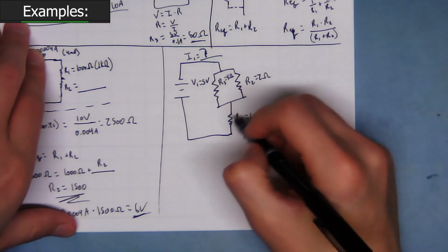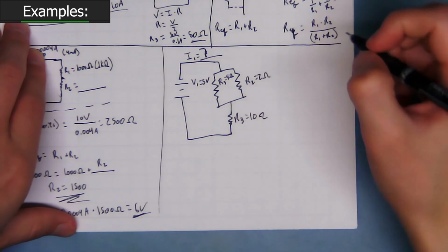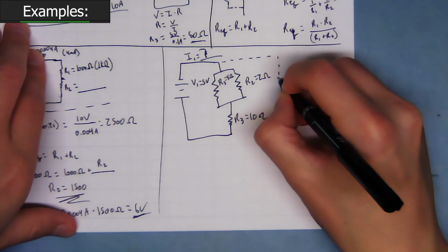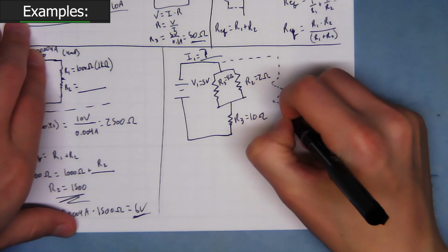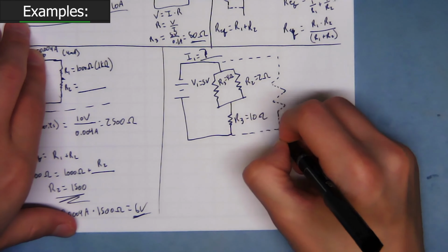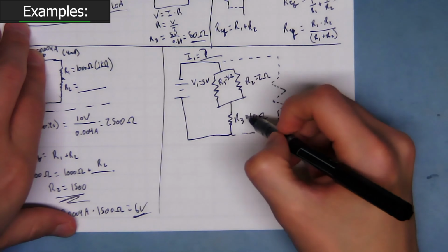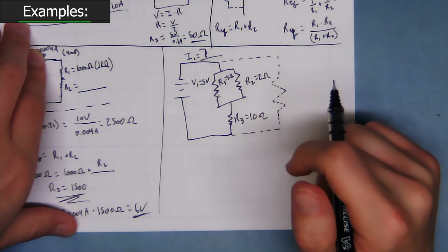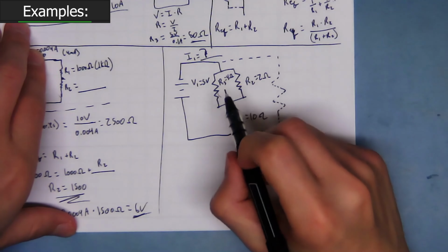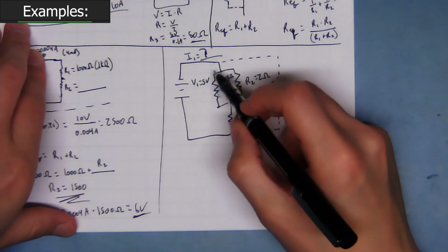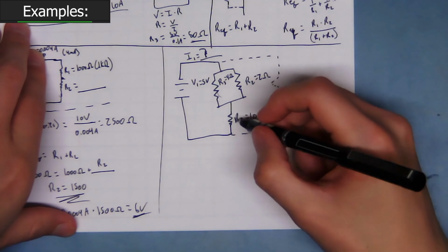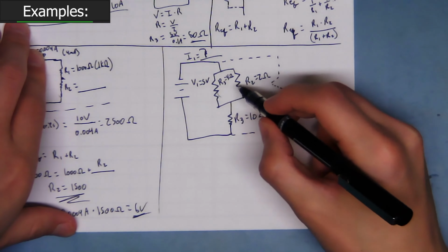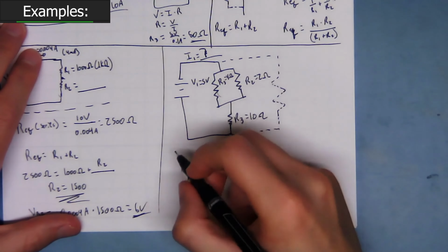So now we've got kind of two things here, right? What we really want to solve for is, if I just sketch this in, this is what we want. We want this equivalent resistor, but that involves both a series combination and a parallel combination. So that is not straightforward. How do we do this? Well, we can't directly apply our series formula, right? We can't say R3 plus, no, it's R3 plus the equivalent resistance of these two. So let's start with the parallel combination to simplify this.